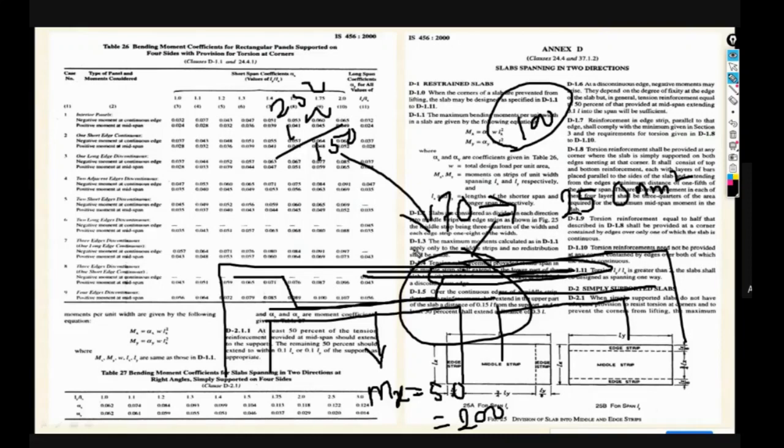Okay, all the elements. So which method is then economical, the bent up bar method or the curtailed bar method? Four to six years before, the bent up bar method was used. Right now structural engineers are using curtailed bars, that means they are curtailing the bars at the bottom and providing extra top bars at the top level, just above the beams.